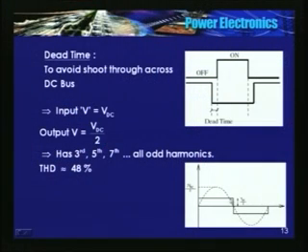The output voltage waveform is a square wave, and I called it a DC to AC inverter because the average value is 0. We are interested only in the sinusoidal component whose frequency is equal to the frequency of the square wave itself.